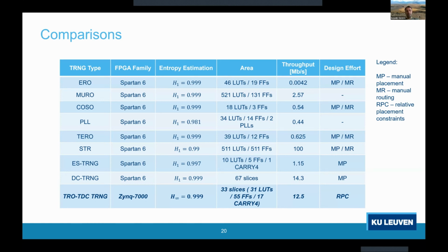For example, in an embedded device, you may need to generate some keys before you boot, so this has to happen at very early boot stages. Essentially, the longer you have to wait for the random numbers, the longer the boot process becomes, and users don't like to wait. Then people formulate the requirement that they need a high throughput. But actually, they just need very few bits, but quickly.